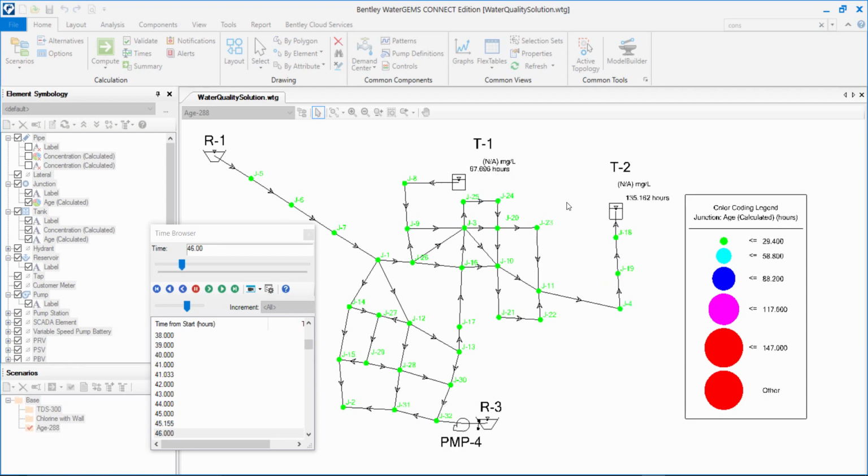They kind of create old water because it takes a while to turn over the volume of water in that large tank. So this is some of the benefits that you get to see by running a water quality model: predicting where old water is, what the decay rate is, or what the chlorine value is somewhere in the system based on a decay rate. And also look at some nice behavior over time. If we wanted to, we could also graph concentrations over time leaving a tank or something like that. So there's lots of different ways to express the data.